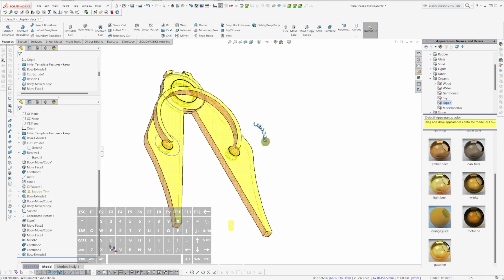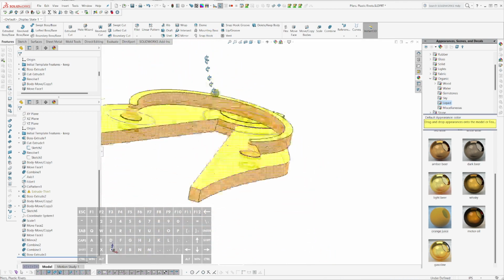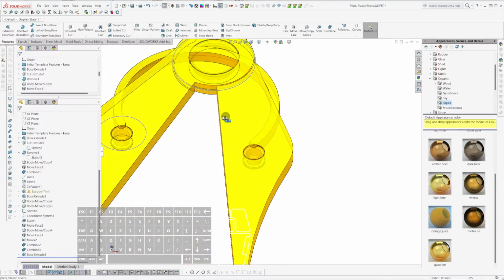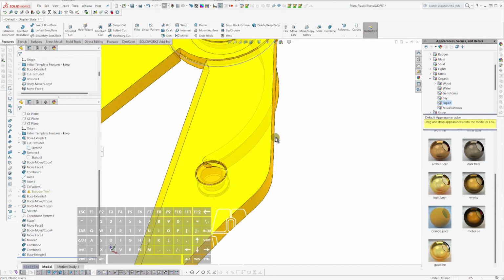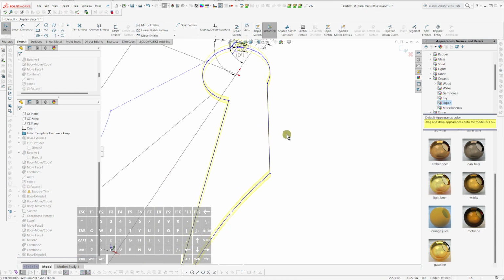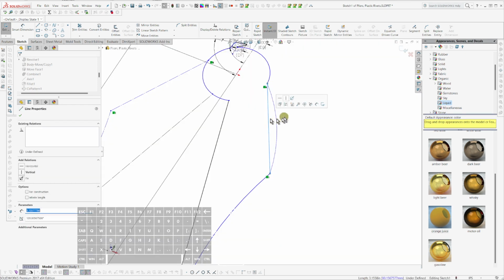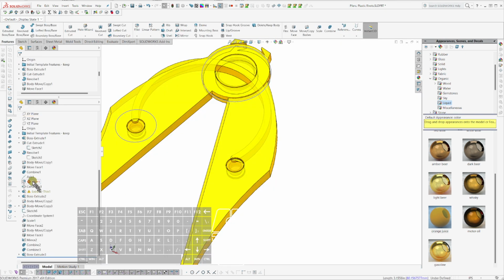And I need to... doing that has almost precluded the necessity of supports. So what I can do is just modify the shape a little more, and then it will preclude them. So I'm just going to go like this. I know I'm going to break my fillet, but I'm fine with that. Let's make this construction. Rebuild. Redefine the fillet.